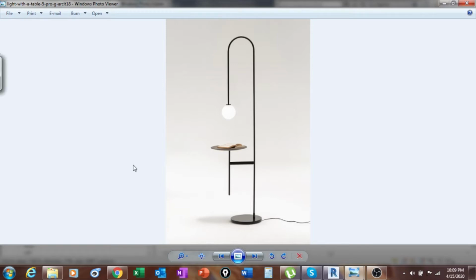I'm going to bring the picture inside Revit, and I'm going to scale it. So the total height of this piece, I'm going to take it from here, from this point, because this has a perspective. This point is closer to you than this point here, right? So I'm going to try to take this point and this point. And I'm going to ask Revit to make this distance 1,900 millimeters. Once I do that, I'm going to have this whole piece to scale, and I'm going to start tracing it to create my family. So let's go for it.